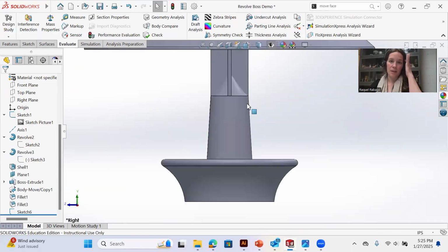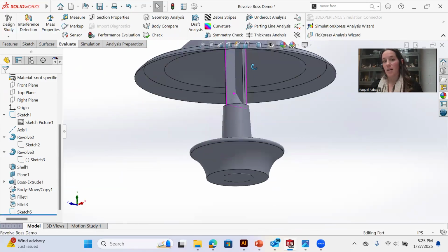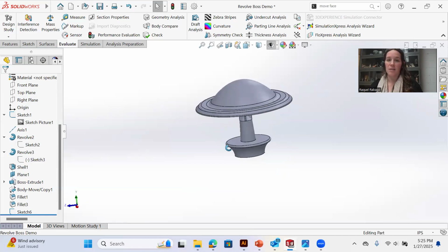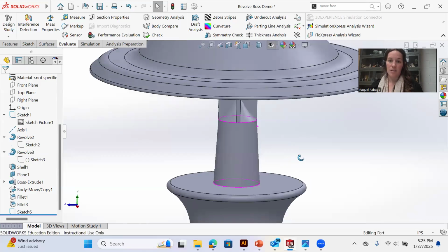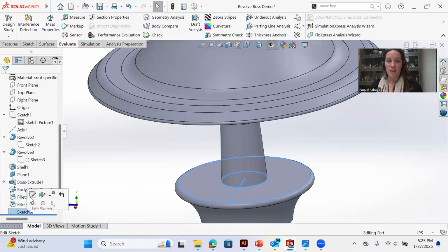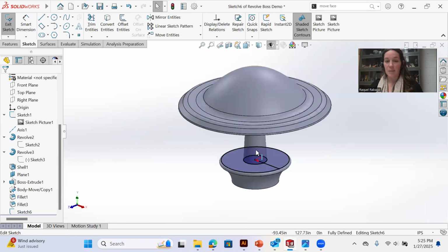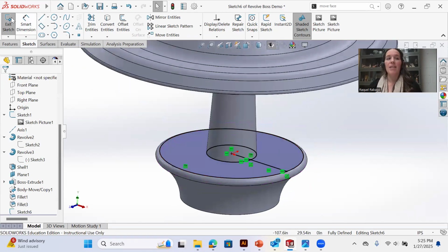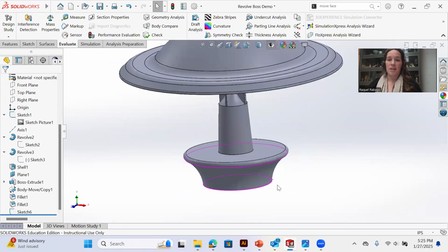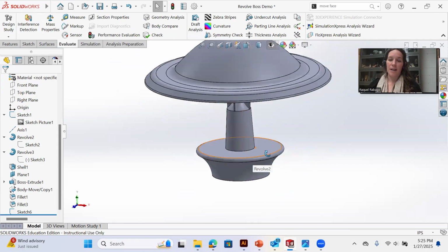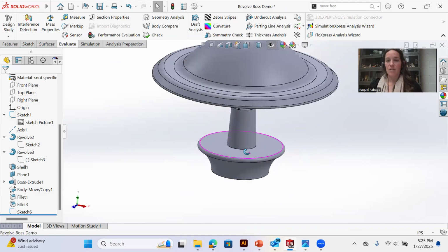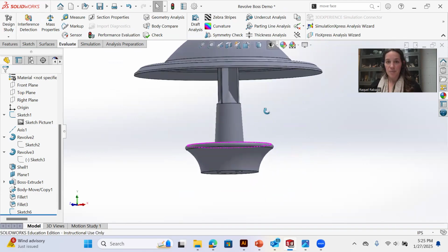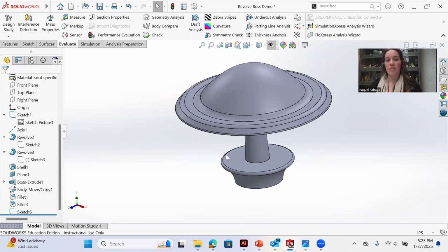And let's see. Now we did that, we adjusted the width of this top, and the top rebuilt just fine. So it didn't need our help in finding out where it was going or where it was supposed to be. So I think that was pretty successful. And then we can look at our measurement sketch again. It's going to update to show us that length of the seat now that we've changed a couple things, and it's 18 inches. So that seems a lot more reasonable. So it's 18 inches off the ground and it's 18 inches to the back. So you could maybe sit a backpack and yourself on it. So that's a super quick revolve.